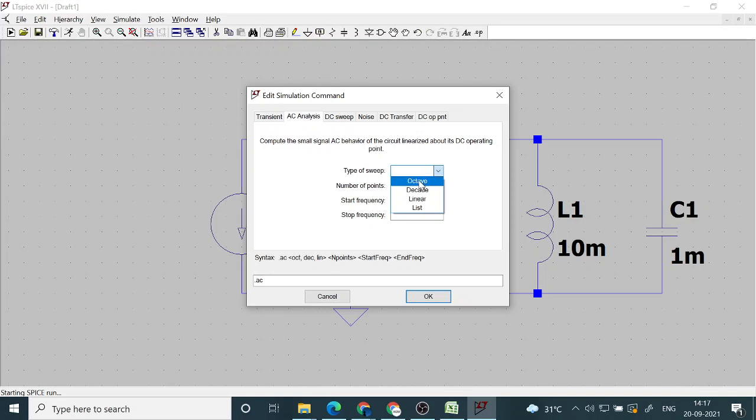And if it is octave, that is yet another way, like you go in by factor of 2. So if you are starting with 1, then you go to 2, then from 2 to 4, that is like a unit distance, and then from 4 to 8, another unit distance, 8 to 16, another unit. So it's like multiplication by a factor of 2. In musical scales, octave is a very important way of showing frequencies, because the sounds have some relationship when it comes to harmonics.